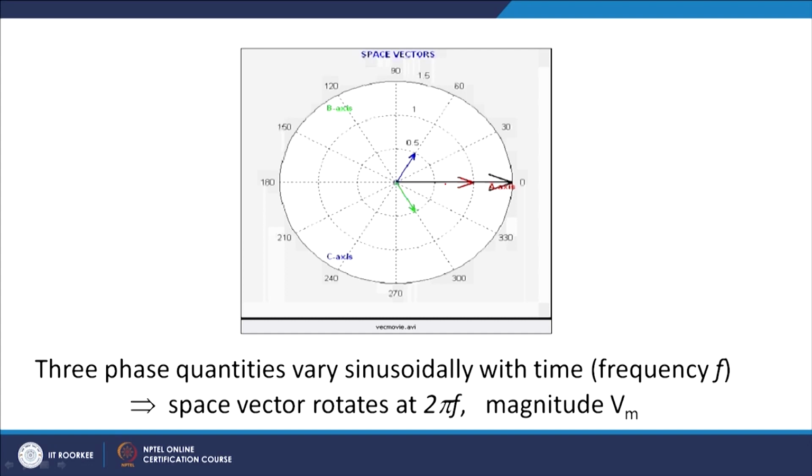So, let us see that. For this reason, we have chosen a space vector, where I assume that we should align one of the axes with alpha and another axis with beta. We shall use the concept of the alpha beta frame or the DQ frame, where DS and QS are the stationary frame and DR and QR are the rotating frame.